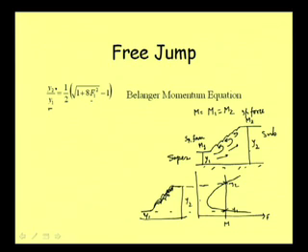Well, now this Y1 and Y2 are called sequent depths, and this has a definite relationship based on the Froude number of upstream, that is the Froude number here, F1. We can calculate V here. Suppose V1 is the flow velocity at this point, then V1 by root over gY1 is called F1, and based on this Froude number we have a particular depth Y2 at the downstream point of the hydraulic jump.